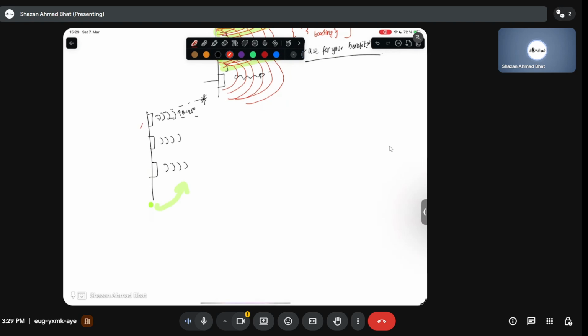So what you do is you give the excitation, and you give different excitations with different phases. Essentially you give an excitation of 0.1 pi. I'm just assuming some numbers. Let's say you give 0.4 pi, 0.6 pi. And because there are different phase differences between the excitations, that will get reflected in the electromagnetic waves itself. So when the electromagnetic wave is radiated, it will have a certain phase difference of 0.1 pi. From this, it will have 0.4 pi. From this, it will have 0.6 pi.